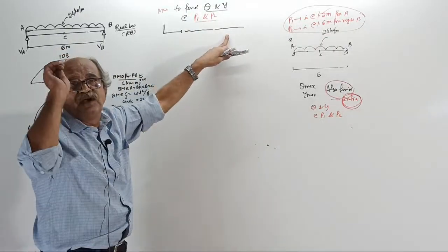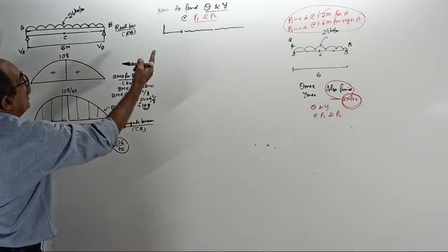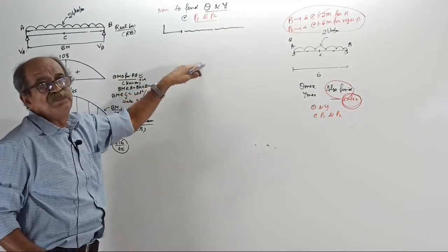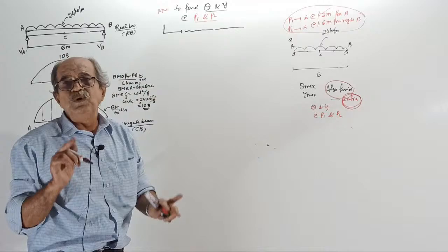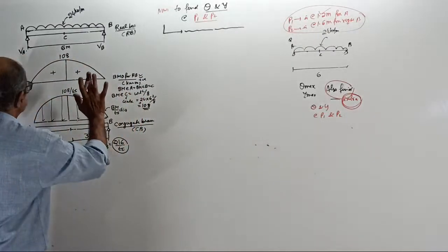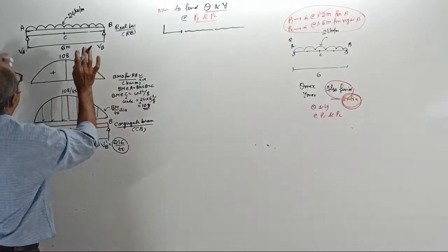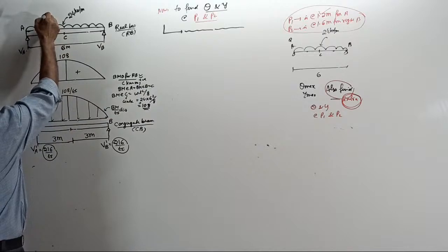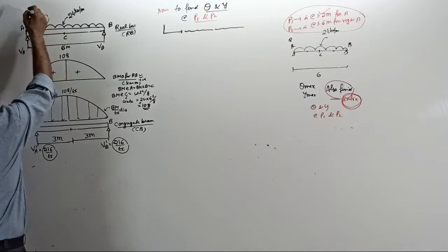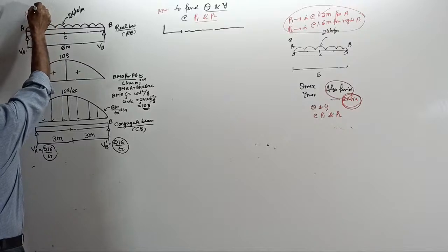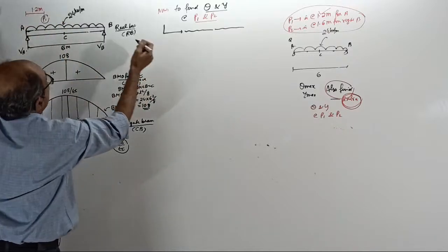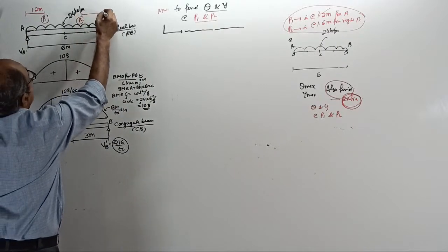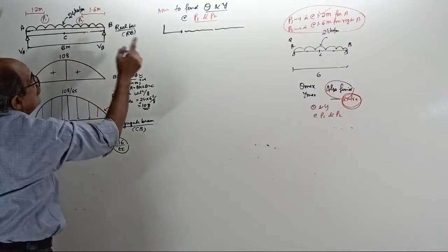First, go back to the system and mark the points P1 and P2. Actually, 2 points are there. Or any point. If they want only 1 point, mark that point without disturbing the main thing. This main marking, you should not disturb. P1 is at, see, this is 3 meter. 1.2 is here. Light line. Without disturbing, P1 is at 1.2 meter. P2 is somewhere here, at 1.6 meter from there. Mark it. Okay, write it here.